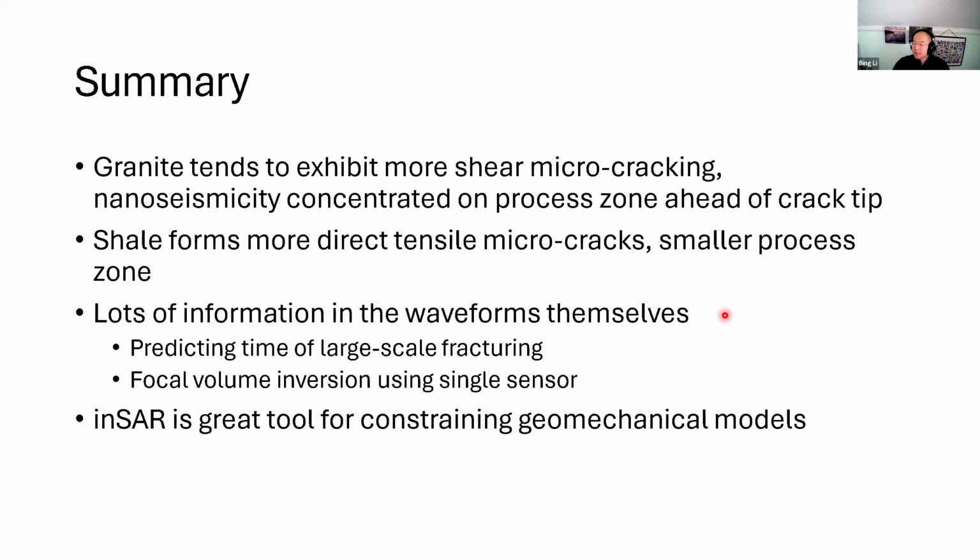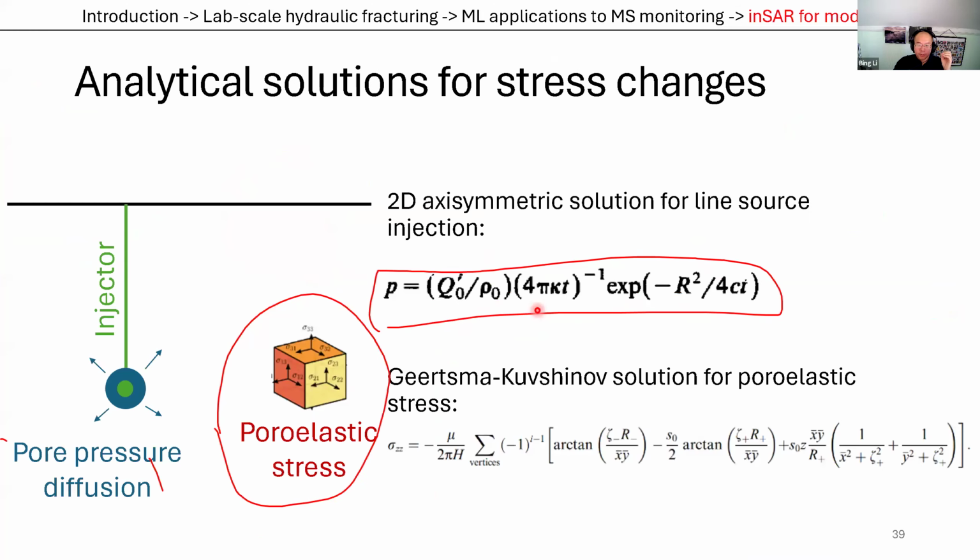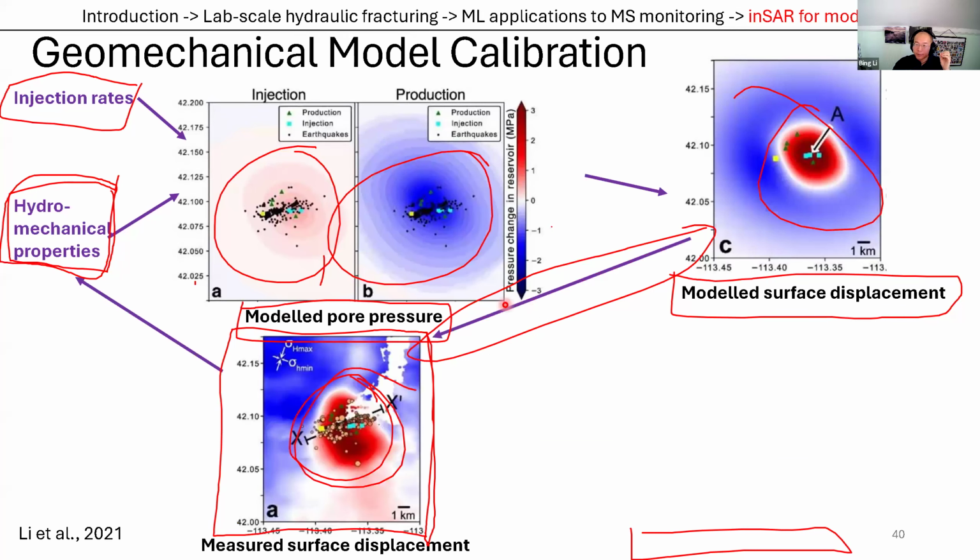Absolutely. I didn't mention this, but the InSAR data is actually only single track. I think it's either ascending or descending. So it's actually only line of sight. It's not even vertical displacement, it's sort of an oblique displacement. So what we've done is, when we construct our model and we model the surface displacement, we are only decomposing that into the direction of the line of sight. So we're comparing apples to apples in this case, only along that given direction.